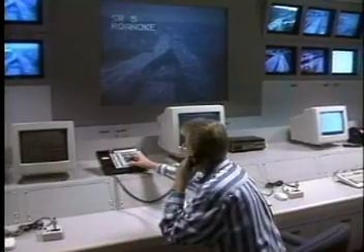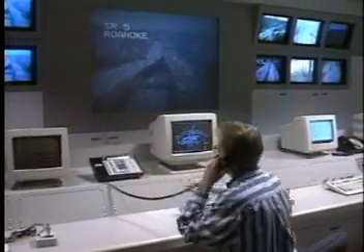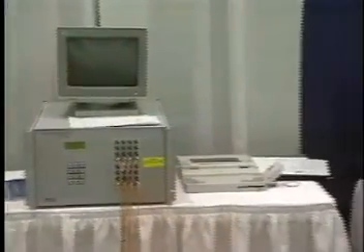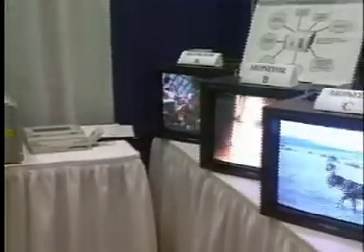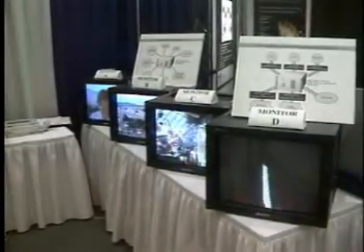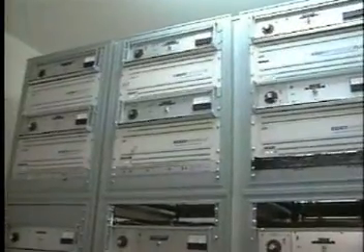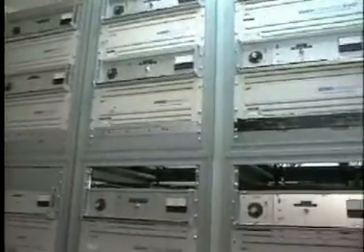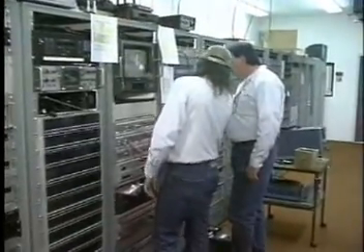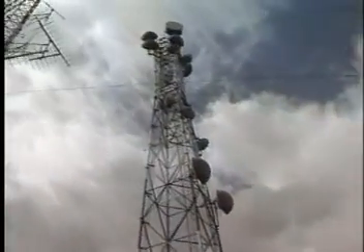What makes it better than other types of transmission line? Fiber has a number of distinct advantages over other methods of signal transmission, the most important of which is bandwidth. Bandwidth is a measure of the information carrying capacity of a transmission system. The amount of information that can be handled is limited by the frequency of the carrier signal. The higher the frequency, the more information can be carried. This is why microwaves can carry more signals than radio frequencies.